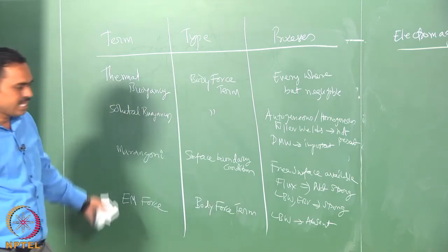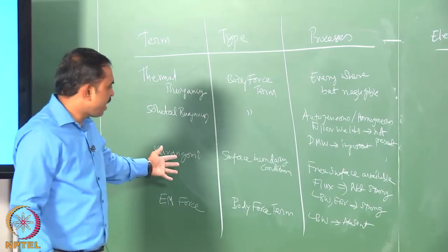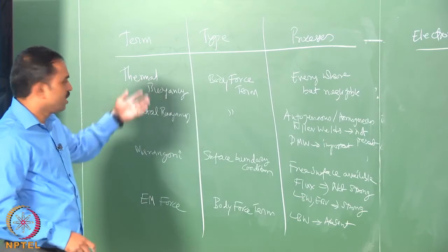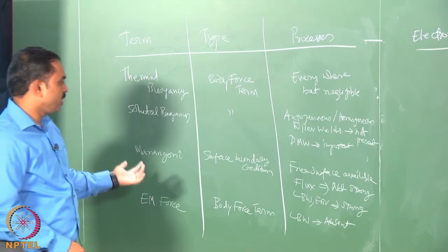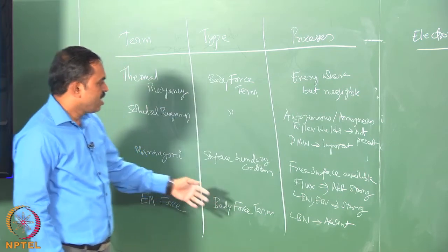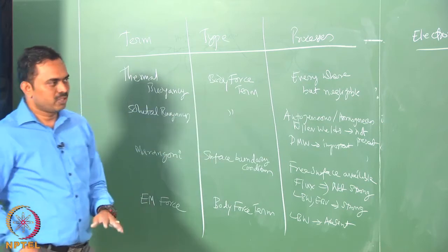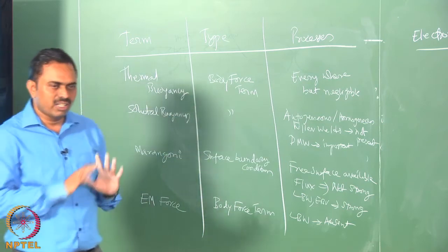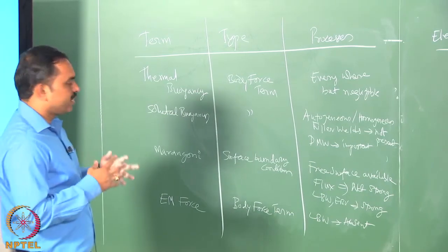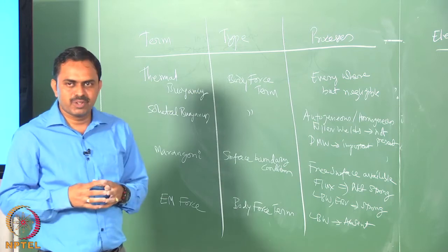Okay. So, as you can see, the different driving forces are to be kept in mind, and depending upon the welding process you must choose which of these are active. Some are boundary conditions, some are body force terms which come in the equation, and some can be neglected in some conditions and some cannot be. So, not all are used in every situation, and one must pay attention to the process conditions to pick the right kind of term for the fluid flow.